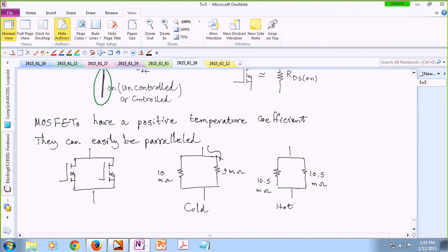Okay, so to summarize things, we talked about diodes. They are passive switches. They don't have a control terminal, and they are actually a second quadrant switch device. Or you can flip them and turn them into a 4-quadrant switch, basically. We talked about IGBTs, and they are first quadrant switches, and then you can flip them so that they turn into a 3rd quadrant switch. And then MOSFETs are actually mostly used for the 1st quadrant, but they can also handle the 4th quadrant as well.